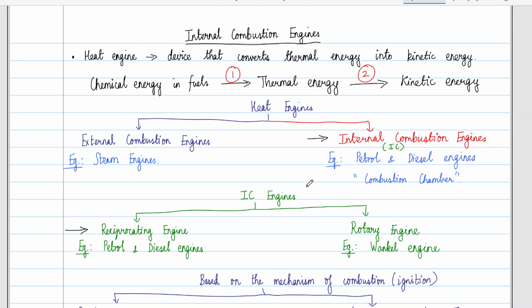The first force is the force you need to push the vehicle, Fx, which will come from the torque. You can replace that Fx with the torque on the rear wheel, multiplied by two because you have two wheels, divided by the radius to get the force. This is the force which you are going to use in your favor.